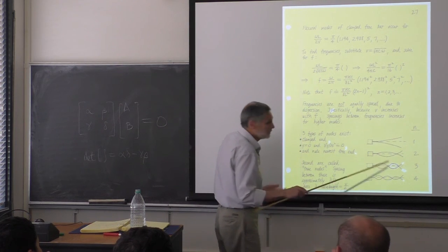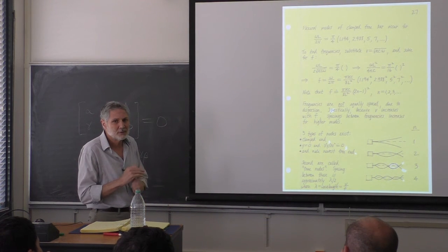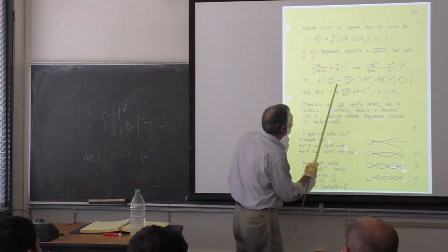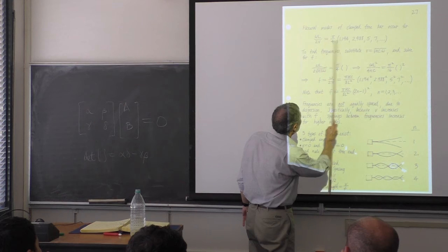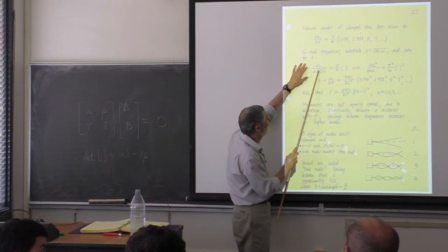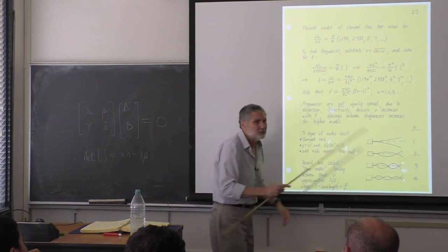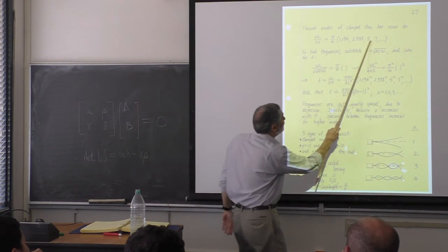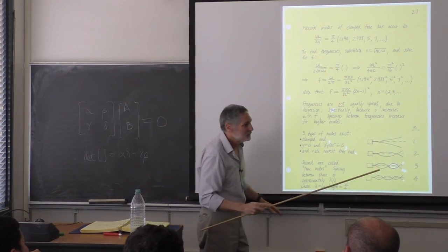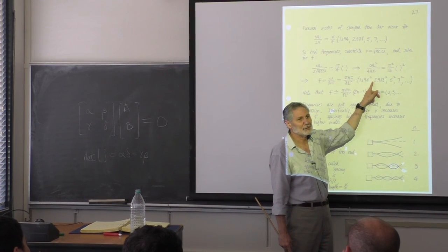So we're going to solve for the frequency here. This is the frequency spectrum, the standing wave, the normal modes for, what type of bar are we doing? Clamp free, right? Okay. So when you track this along, we keep using this notation, and because of the dispersion here, because V is not a constant, these modes lose their uniform spacing. The uniform spacing you get to very quickly after the fundamental is gone. They get farther and farther apart because of the dispersion.